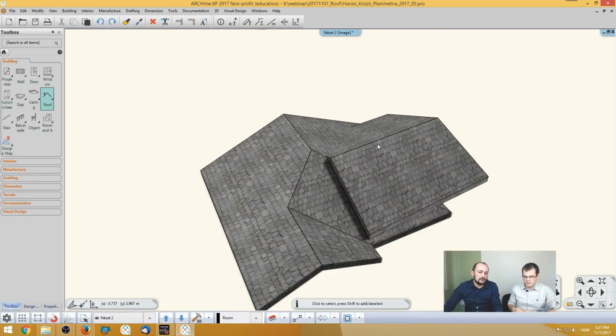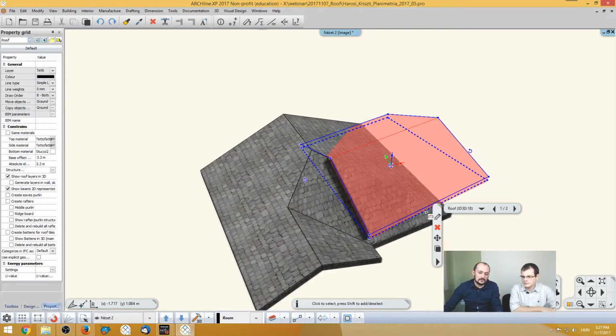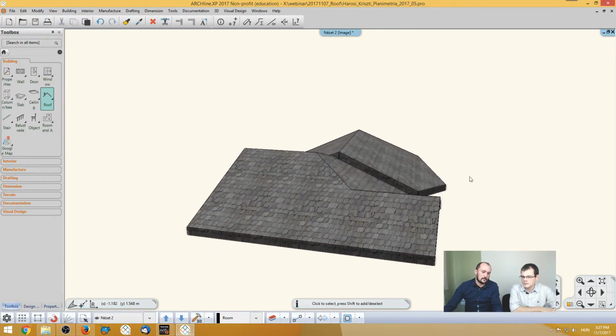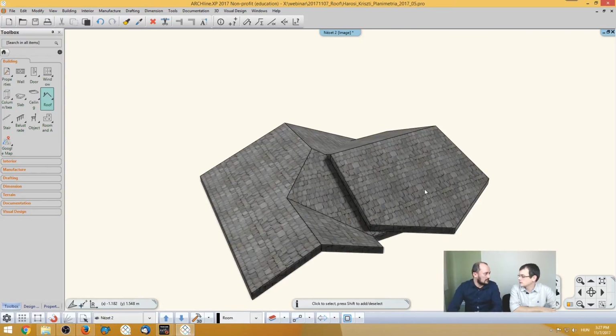But if you would like to change only the shape of this single roof plane, then you do not edit this dashed line, the structural line, the structural contour, but you will edit the roof plane contour, which is this one. That's how we call it. You just click here, insert node, and see, now it's still a plane, but it's just a different surface shape. Now let's stay on this topic.